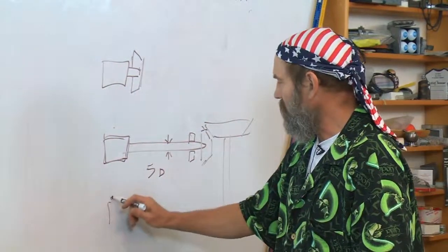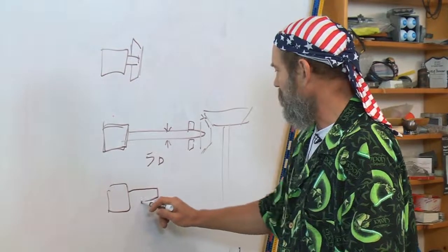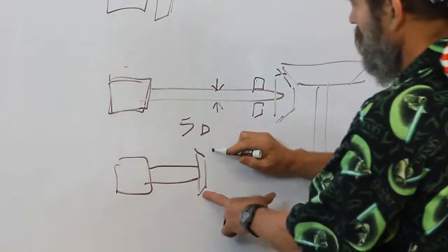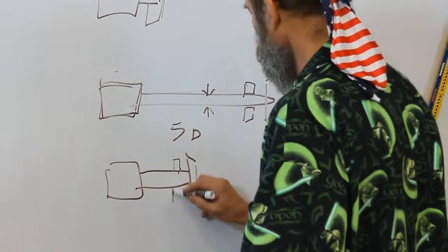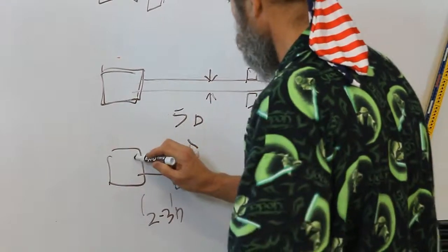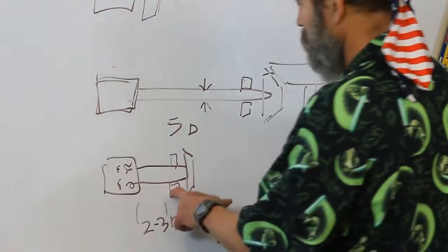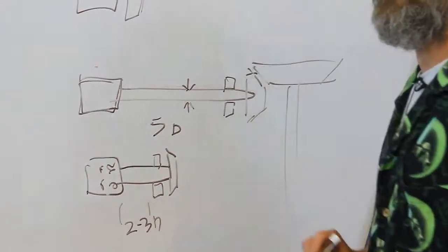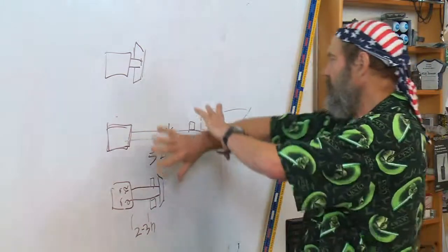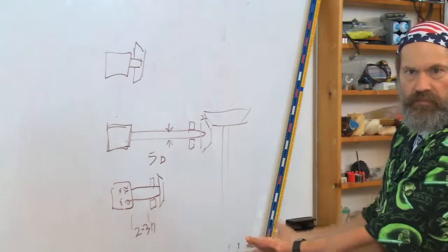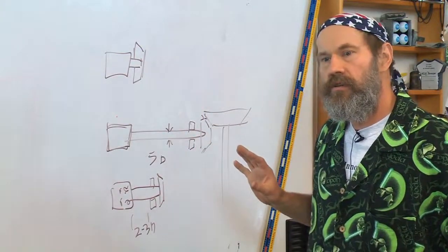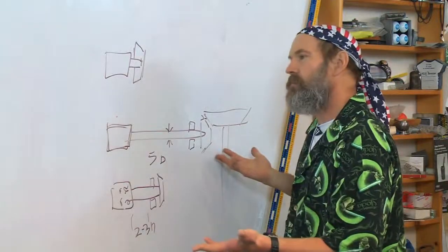Your worst nightmare would be to have a motor with a shaft maybe like that, and the gear, and then a bearing here that maybe was, let's say, 2 to 3 diameters away from the bearings in the motor, because then this bearing would fight those bearings. So this is how, as a design person, you can start to lay out your machine, thinking about where you're going to need your elements, and to be a good design person for that.